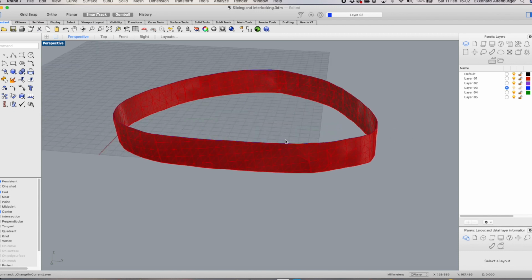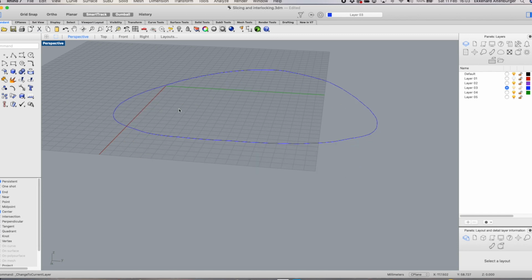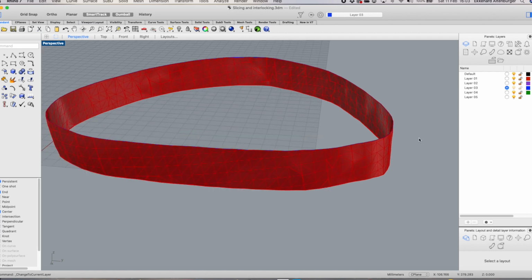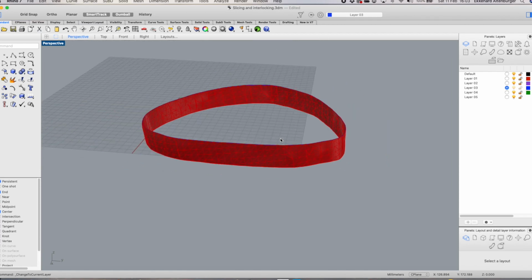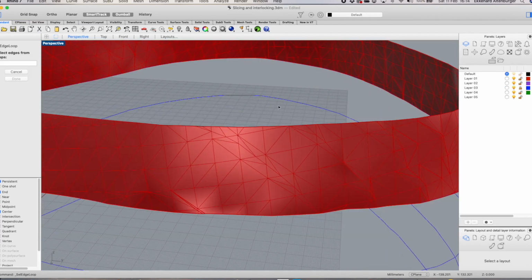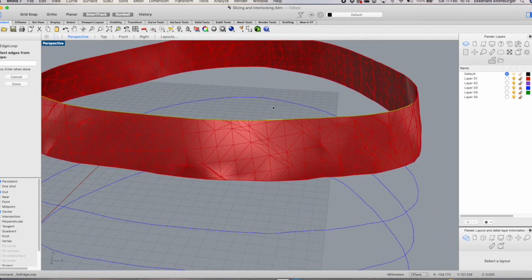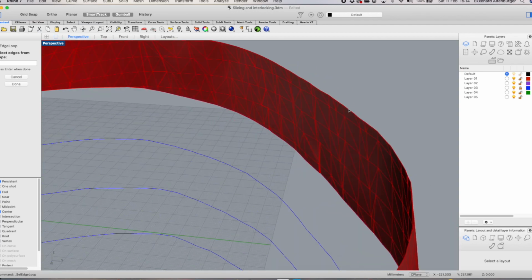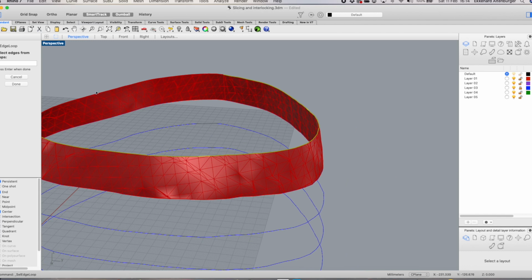You can still see it's blue, and if I hide this one, we have this blue layer. Yeah. So because you need to have it in the right position. If you move it, you will never get the position right again. I need to zoom in, and you need to select this, and now without actually pressing shift, you can select the entire edge loop here.